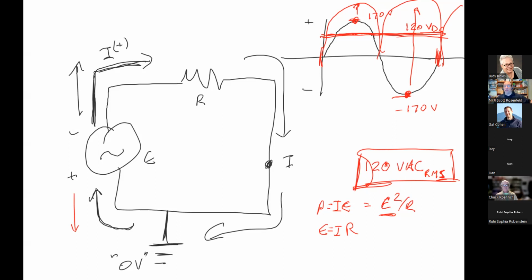Aluminum is actually a really good conductor, except has anyone ever worked with aluminum? And know why it might not be a very good conductor to use? Aluminum can melt very, very easily. Yeah, but especially when it's thin. But we're not talking about melting. It expands and contracts too much. Actually, that's a little bit of it. How about if you have a piece of nice, clean aluminum? How long does it stay clean? It oxidizes really fast. It's very reactive, and it forms aluminum oxide. And aluminum oxide is a very, very poor conductor.